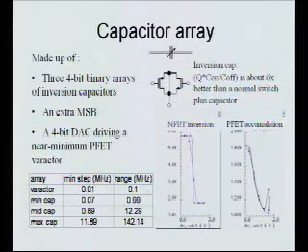So what's a varactor? A varactor is a variable capacitor. In this case, the varactor was an accumulation mode PFET. It's just a variable capacitor. Okay, so that's just the basic idea: rather than doing a traditional analog control, I do a really heavily switched control. If you look at most modern oscillators, there's some hybrid of the two. There's usually some sort of fine analog control and then a coarse digital control. And this was just an extreme version where I made it so digital that the analog went away.